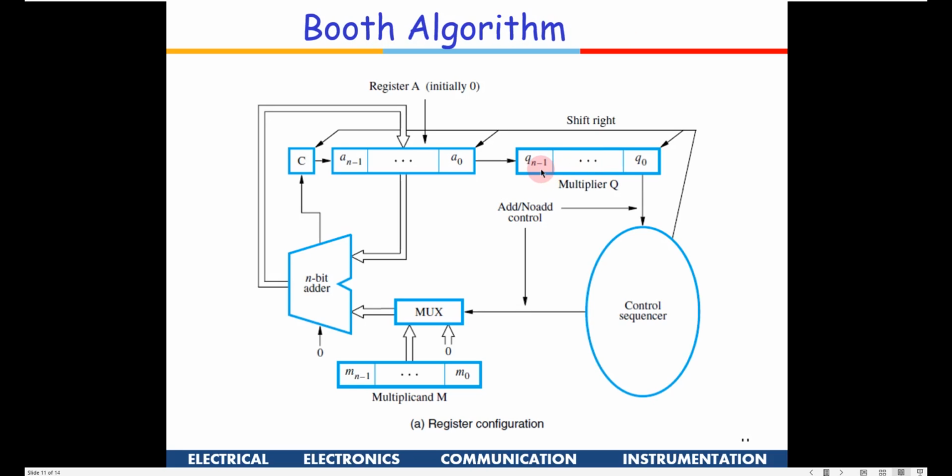So that is known as the multiplier. I am putting the multiplier here and the multiplicand here. Initially the accumulator, this register A, is all 0. If Q is 0, this is a mux, and Q is the control line for the mux. If Q is 0, from this mux I am going to 0 here. So 0 and 0 are going to get added out here.